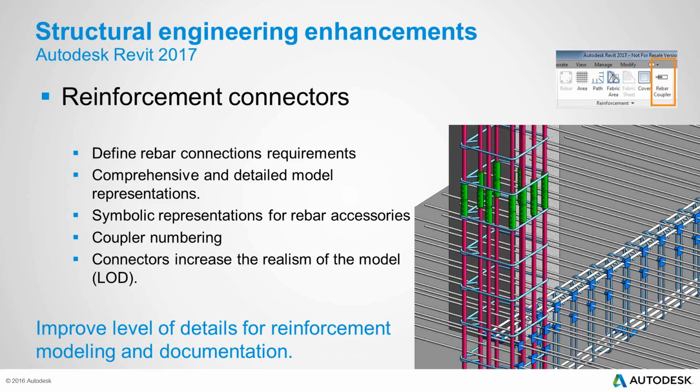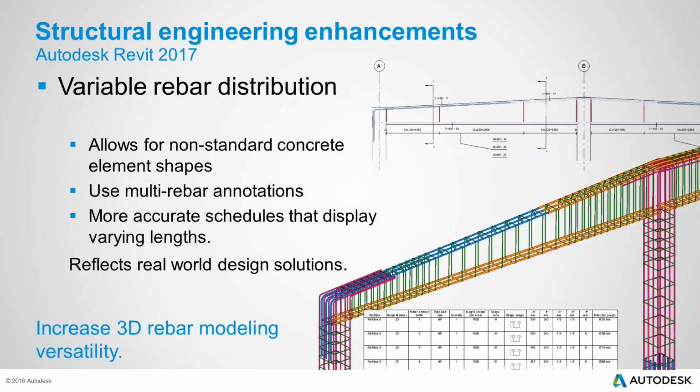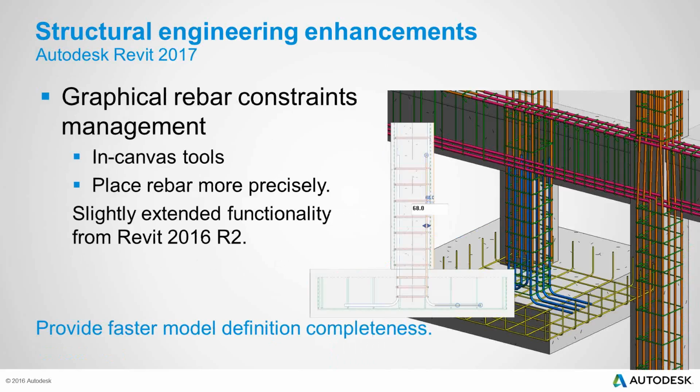So there is a much higher level of realism. If you do a rebar and distribute it through a concrete slab, for example, you can now actually set up different distributions for the rebar throughout the one element, which I believe was not possible in previous versions of Revit.